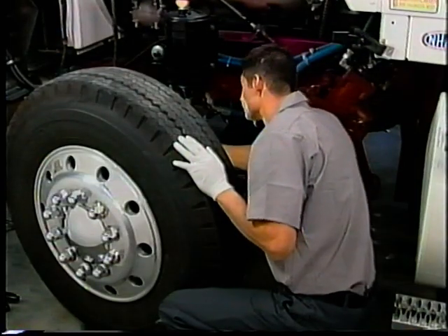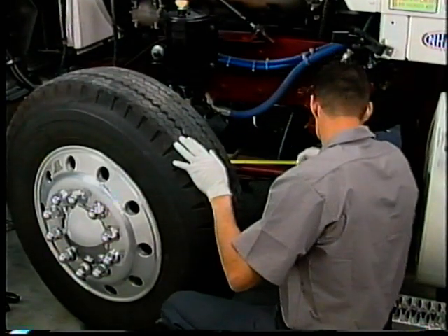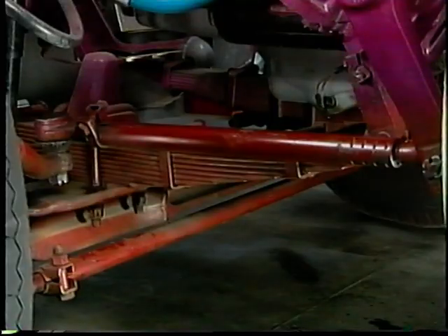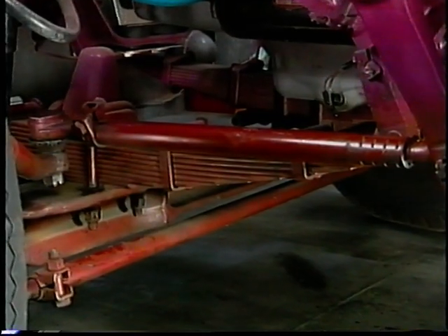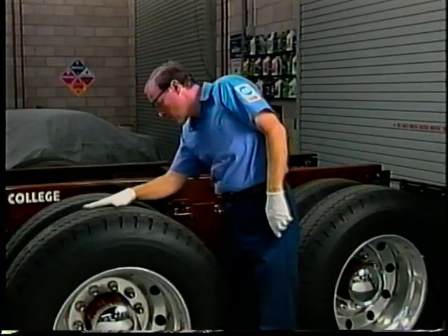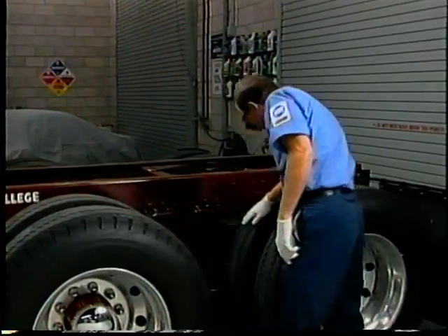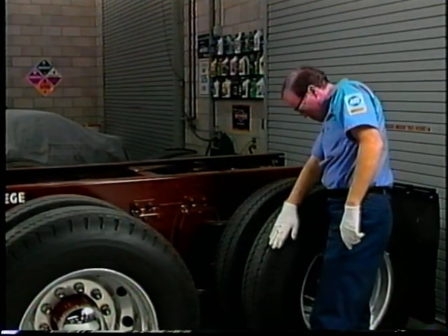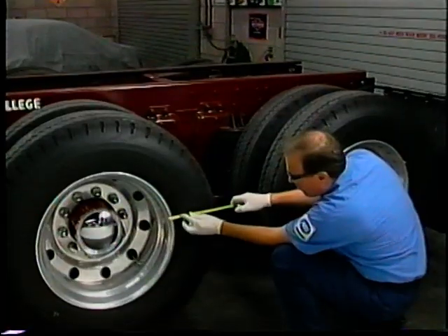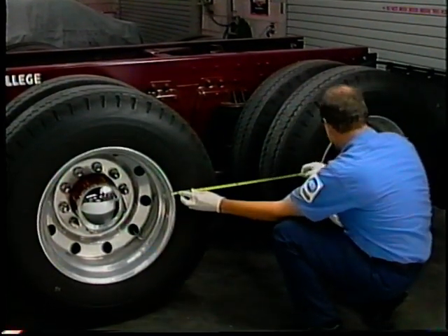Pulling can also be caused by excessive wheel setback on the side that the vehicle is pulling towards. This might be caused by a loose U-bolt mounting or a bent I-beam axle. Similar to a front-end pull is the push created by an improper rear thrust angle. If the rear tires are not aligned with the front axle, they will push the vehicle to one side.